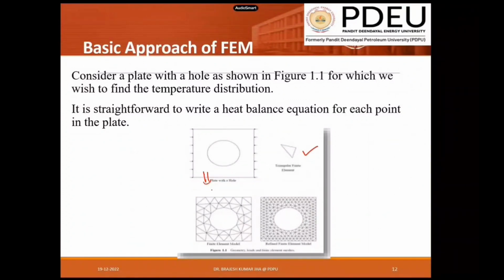First we talk about how such discretization is involved. You can define your element. Once we talk about the element, it has nodes. If it is triangular, it will have 3 nodes; if it is rectangular, it will have 4 nodes. The node is very important in the calculation. You can define the mesh.